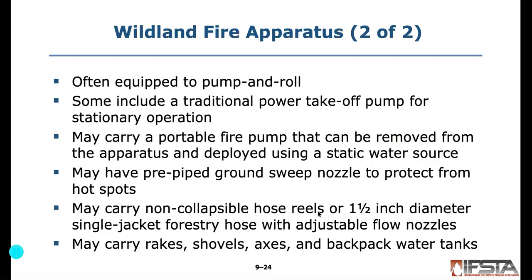Often equipped with a pump and roll. That means the pump can continue as you're driving. All right, so you'll learn some of that as you do some wildland training. And then some include a traditional power takeoff pump. And that means that the apparatus has to stay stationary. It can't drive. Pump and roll, you can drive and pump water at the same time.